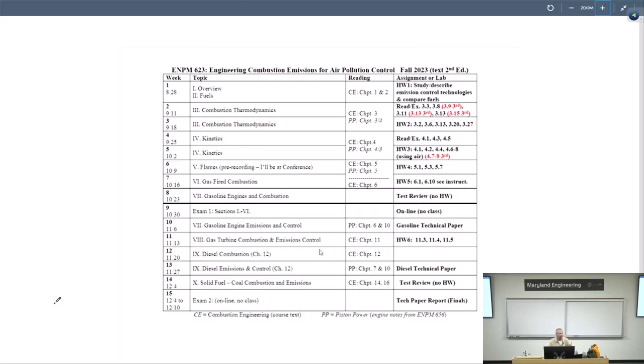In the recent past and into the future, it's largely pre-mixing air and fuel as opposed to diffusion flames historically. So emissions have come down, and they will continue to do so in the aviation gas turbine world. I believe, coupled with some synthetic or e-fuels, that will be the way we can get to low carbon or carbon neutral in the coming decades.